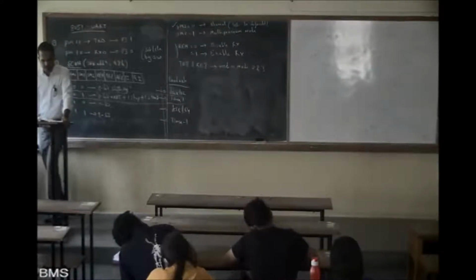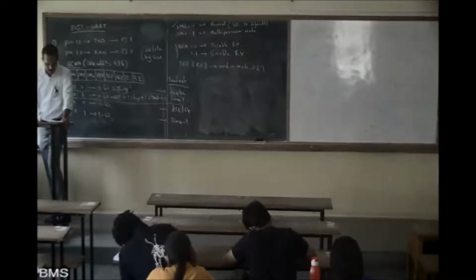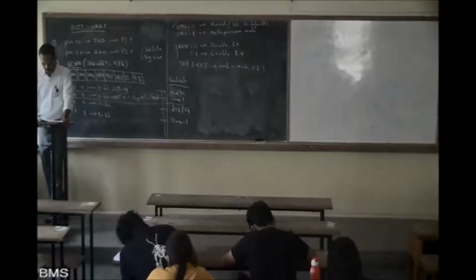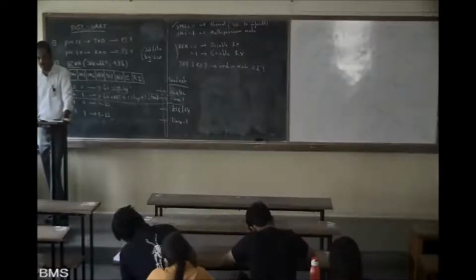TI equal to 1 is set by hardware when the 8051 finishes transfer of a byte. Write it down: TI equal to 1 is set by hardware at the beginning of the stop bit.